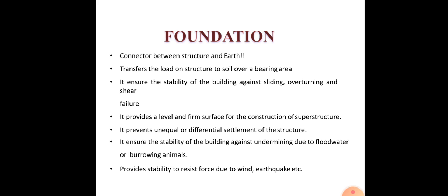So in the event of a flood, the water will gush and may lead to soil erosion, etc. If a proper foundation is given, it will act as a protection for the building. So we can say that it provides stability against the undermining due to flood water or any burrowing animals. And it also provides stability to resist the force due to wind, earthquake, etc. So these are the functions of the substructure or the foundation.